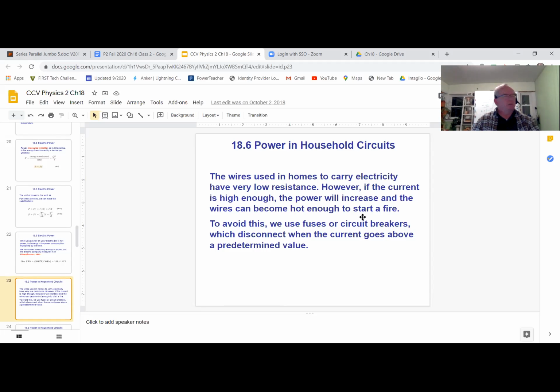So usually what happens with the wires is that they snake. If they're going vertically, they're going to snake along studs, which are the supporting pieces of wood behind the sheetrock. And they're usually back at least about an inch or an inch and a half away from the wall. And then the ones that go horizontally are usually down at about the level of outlets. So again, if you're going to start poking holes into things, stay away from the region that's about a foot to 18 inches off the floor.